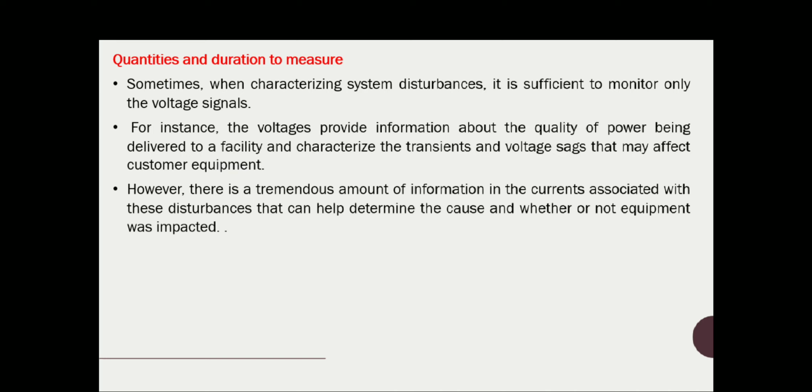And then the quantities and duration to measure. Before going to the detailed analysis, we cannot predict which quantities are to be measured and what the duration of measurement should be. In some cases, in order to characterize the system disturbance, monitoring the voltage signal itself is sufficient.